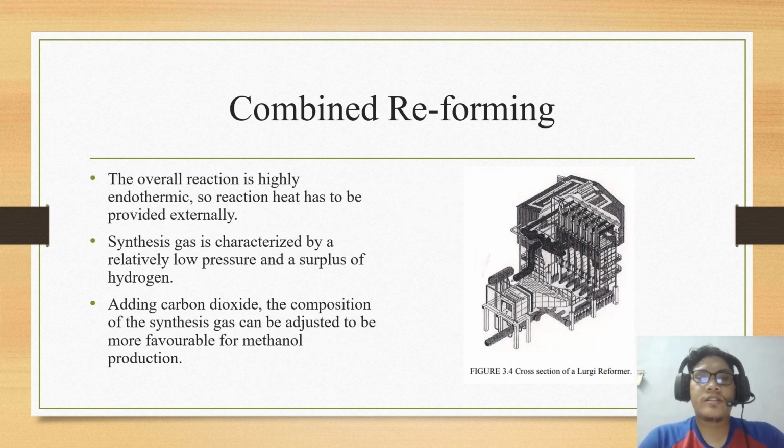The overall reaction is highly endothermic, so reaction heat has to be provided externally. Synthesis gas is characterized by a relatively low pressure and a surplus of hydrogen. By adding carbon dioxide, the composition of the synthesis gas can be adjusted to be more favorable for methanol production.